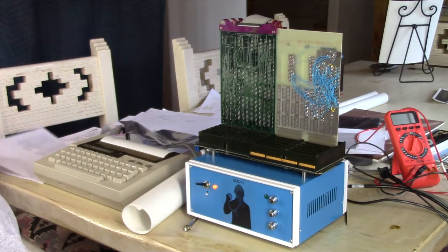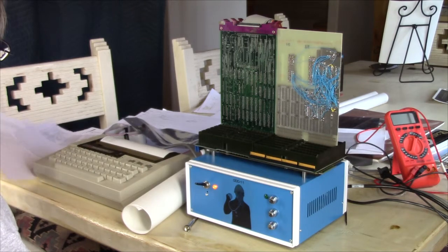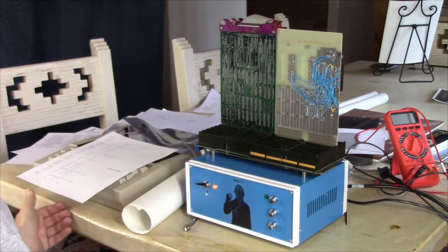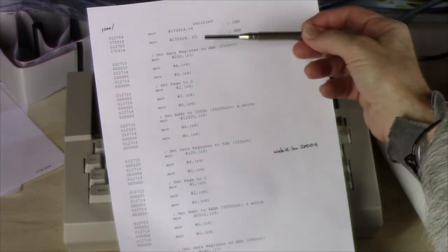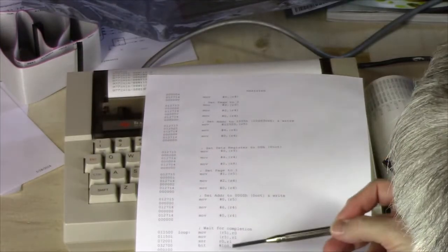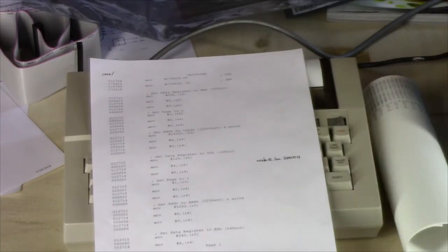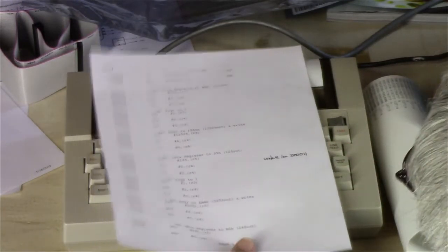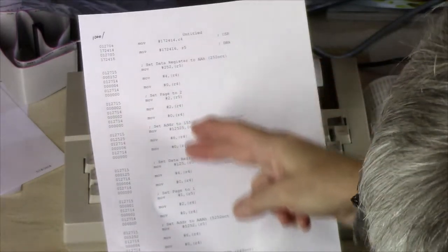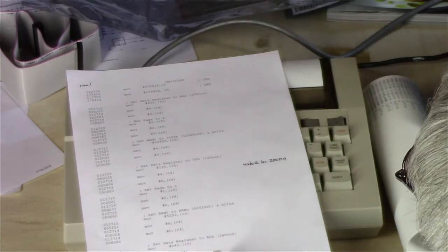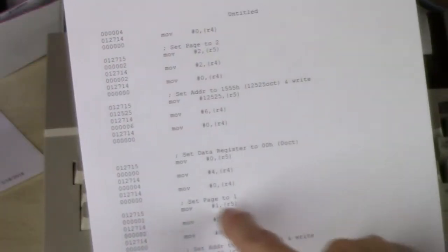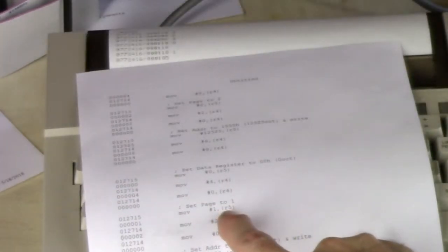In terms of writing it, that's, like I said, a little more complicated and made even more so by the chip itself, which requires a certain sequence of operations before you can actually write the data. So I wrote this program and hand assembled it and ran it before I started this video. What this does is write a 0 into location 0 of page 1. Here's my set page register to 1.